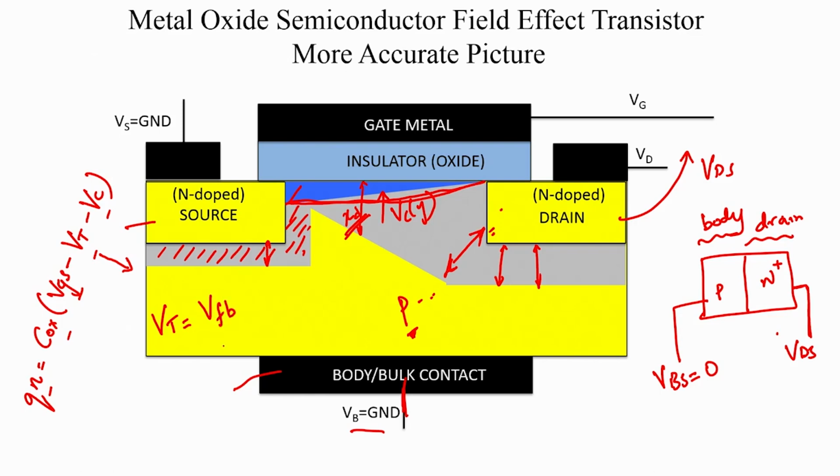You need to put enough charge in the gate so that you are at flat band. Then you need to deplete the semiconductor. In our case the depletion charge is negative, so I will just use a negative sign. And after that we need to increase the surface potential till the surface potential matches 2 times phi f, where phi f depends upon the doping concentration of the p type bulk.